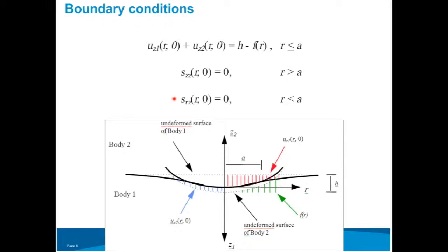When you use a sharp indenter, you are more apt to be adversely affected by friction. If you use an oblique indenter, such as a Berkovich or a flat punch or a sphere, even if there's significant potential for friction, the force resolved along the interface is a lot less. And so even if there's potential for friction, you aren't particularly bothered by it. So when you have friction, Sneddon's equation is less applicable.